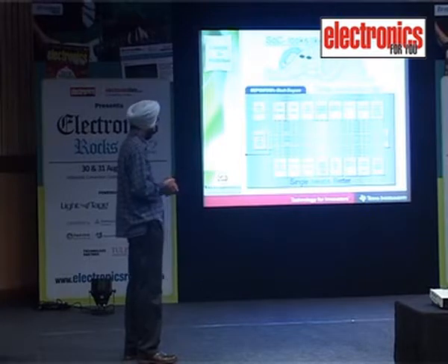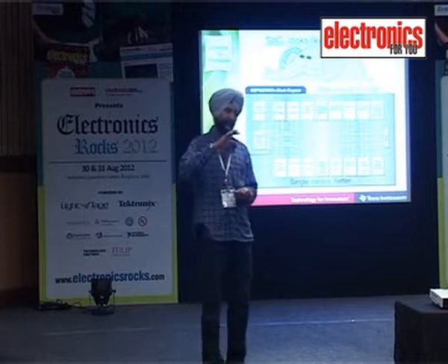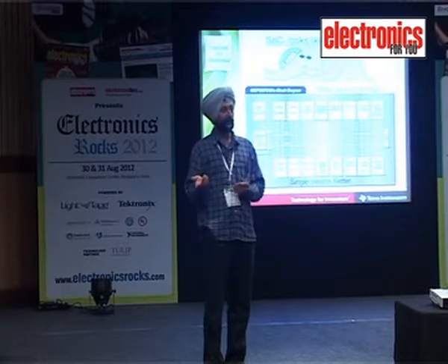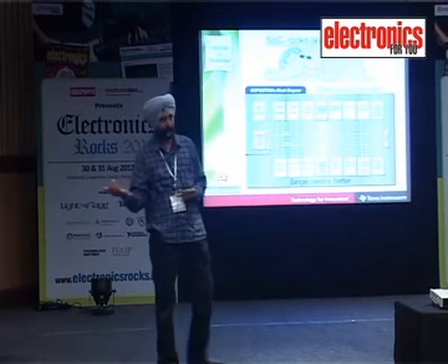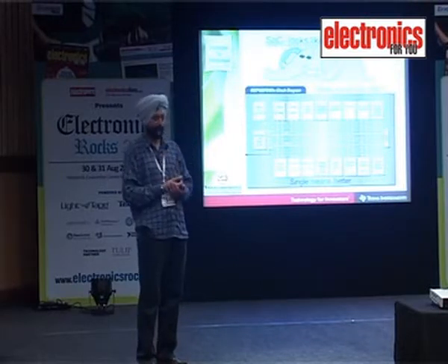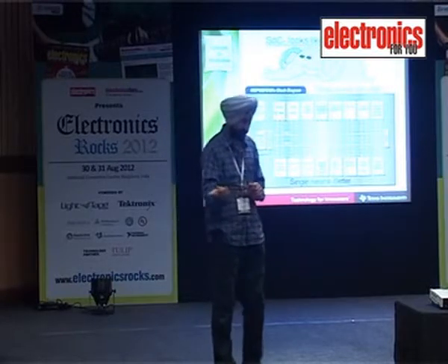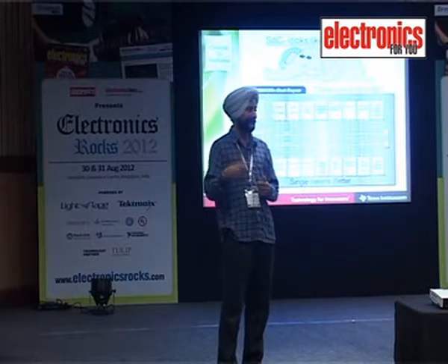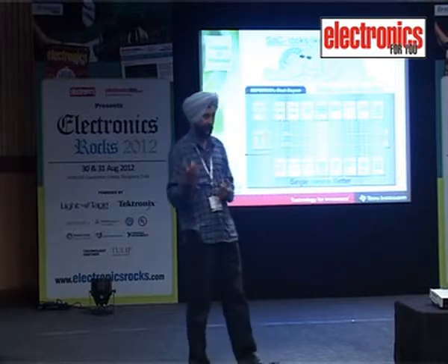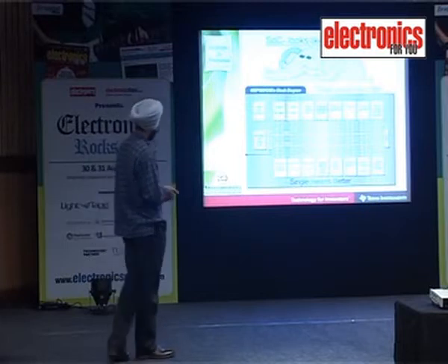So these two timers will be having multiple capture compare registers. So same timer, when you are generating pulse width modulation, multiple pulse width modulations from this timer, at the same time you can use some of the capture compare registers to receive the feedback, like in case of speed control of a motor. So you need multiple pulse width modulation channels. At the same time, you have to take a feedback from the motor. You have to sense the speed of the motor. So you will be having a feedback sensor, maybe a proximity switch or a rotary encoder. So that input can be used with the same timer to measure a speed, right?